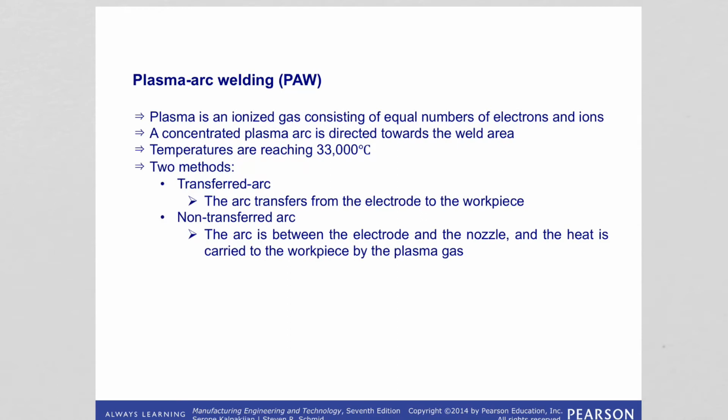And then there is plasma arc welding. In this case, the arc is maintained between a non-consumable electrode and the workpiece. The non-consumable tungsten electrode is set back within the torch in a way as to force the arc to pass through or be contained within a small diameter nozzle.